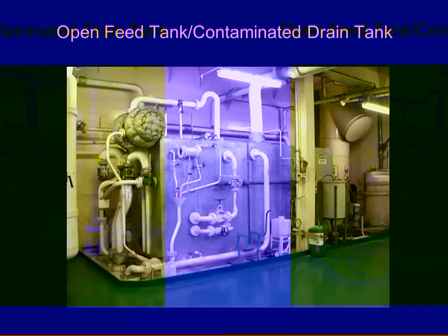So this is a typical looking one on board a vessel. This is, by the way, your atmospheric condenser, and this ship did not have combined cycle. It did not have a steam turbine. So if the pressure in the steam drum gets too high out at sea when you're on waste heat recovery, all that happens is the excess steam is dumped into this unit, and then the water transfers into the tank.